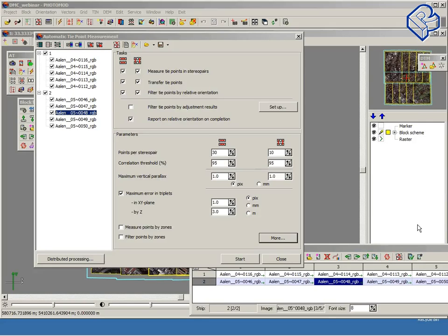Another question is about point distribution between strips, inner strip points. How many points on average do you recommend per strip? One every image, one every 2-3 images, or another value? Again, for the solver, it's enough to have several points in total in the interstrip area. From classic photogrammetry, or from Russian regulations, there should be a couple of points for every interstrip stereo pair.